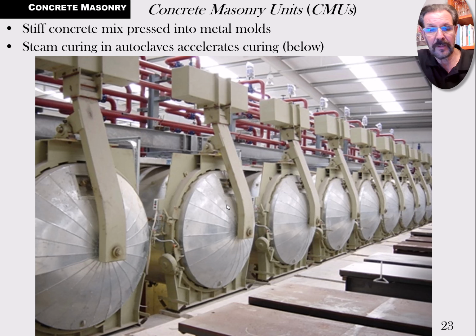In modern times, this is showing the tail end of a concrete masonry block factory, a concrete masonry unit factory, where they run these, when they're standing up, so they can dry out. And so they run them in steam autoclaves that actually accelerate the curing and keep the concrete from drying out. They don't literally overheat the stuff. You don't want to overheat the concrete, but the steam is allowed to become super humid rooms or spaces, or what they end up with in the end.